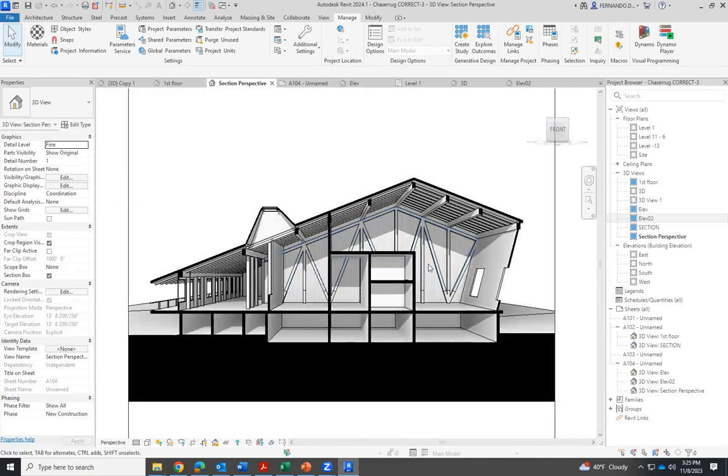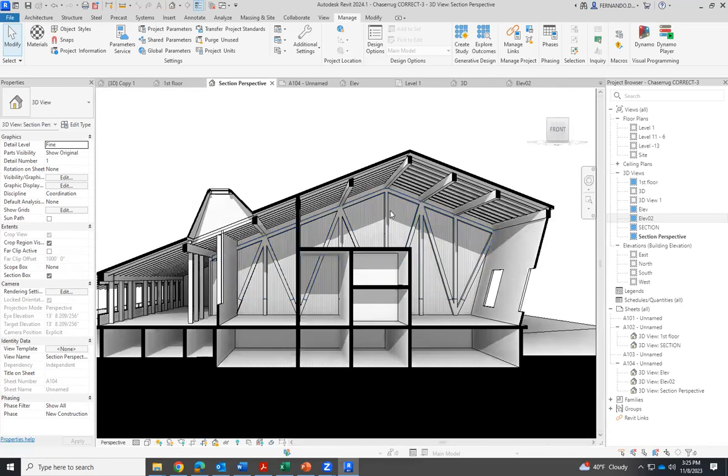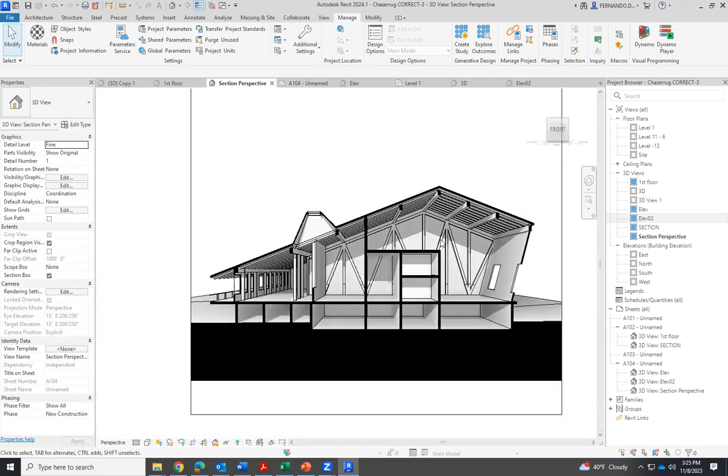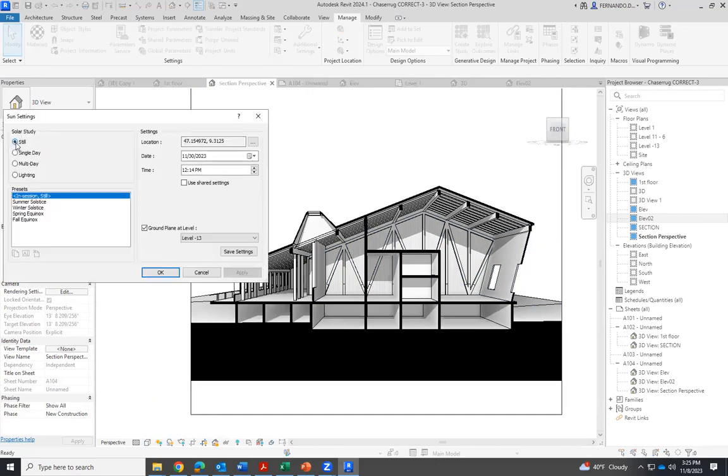Okay, so remember I can use these patterns. Oh, and then the lights. Selecting the right light and shadow is important. So you can select this in sun settings. And in sun settings, if you select still, I think by default Revit uses the day in which we're doing this. So if today is November the 4th, it will apply.